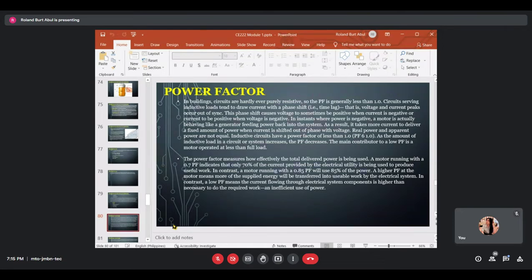As a result, the apparent power and real power are equal, and the power factor is 1. If the circuit in the previous example had been purely resistive, a full 3,600 watts would be delivered to the load rather than the 3,000 watts. A poor power factor makes an inefficient delivery of power.